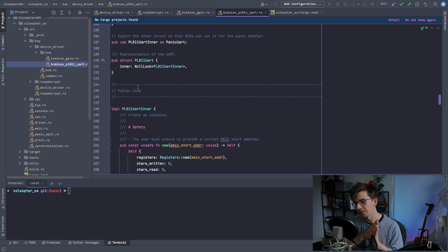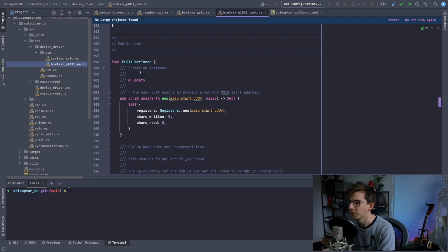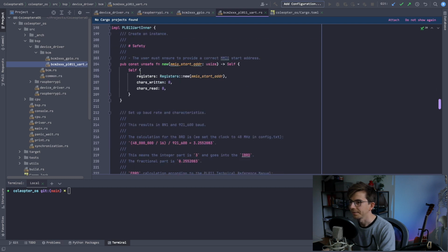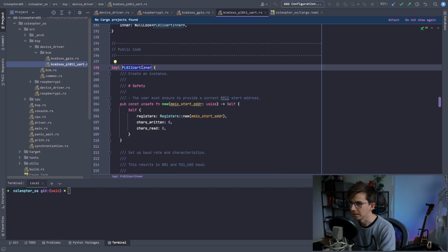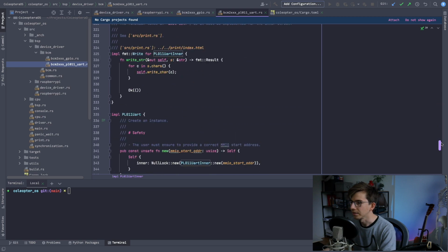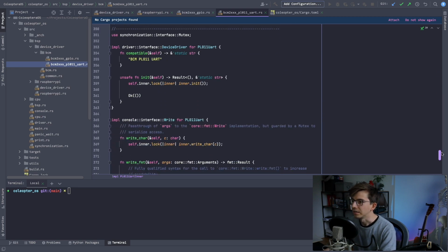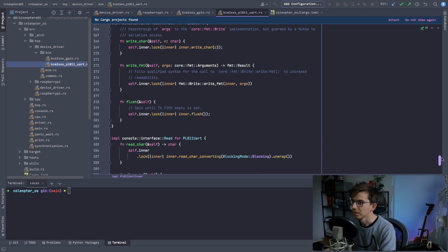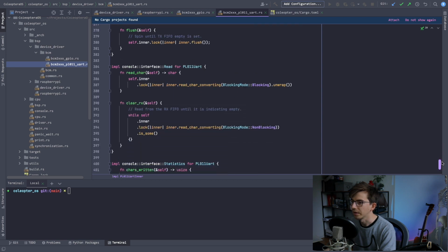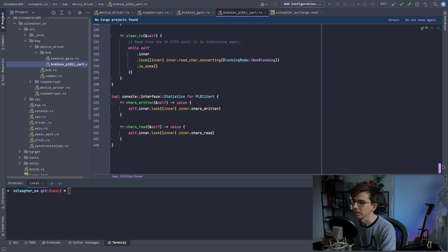We wait until everything is written down into the physical wire, and only after that write something. So therefore we use our mutex and nulllock that we programmed, and this is the inner UART, and down here will be initialization of this driver and all functions that are available for usage.